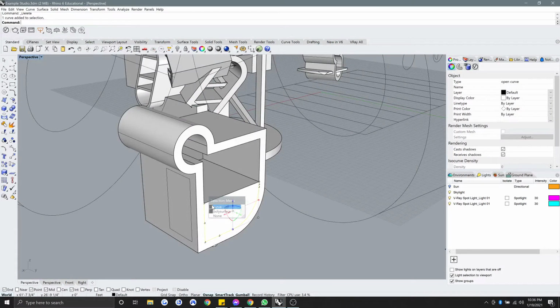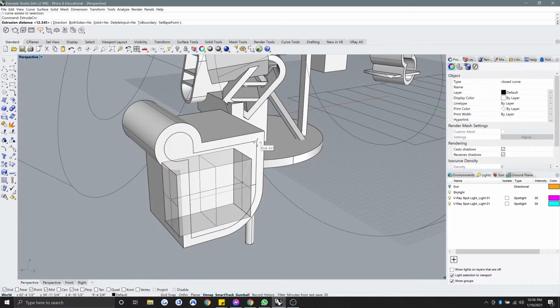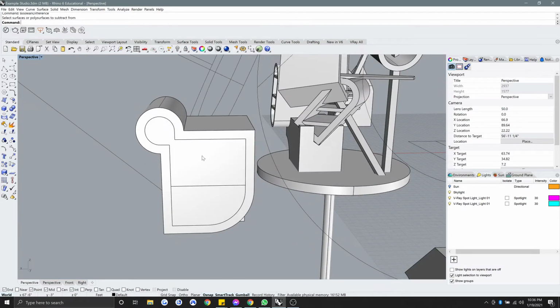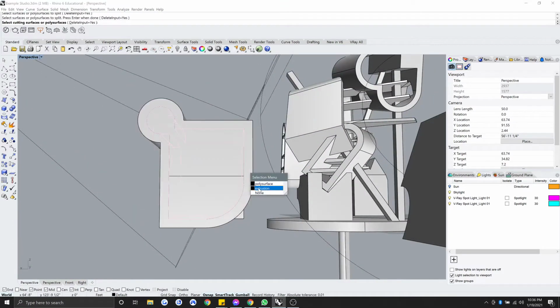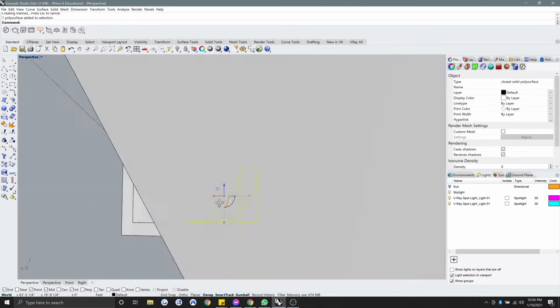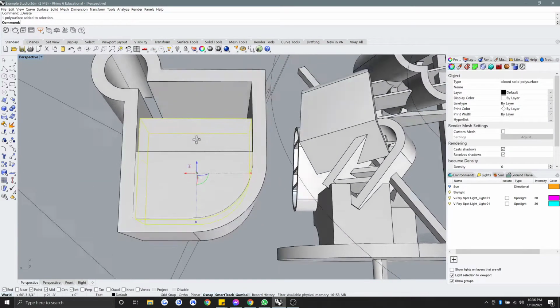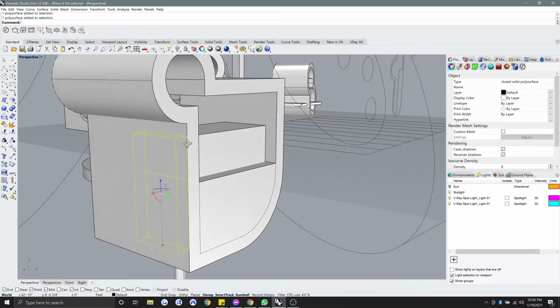On this side, we have the original two curves. I'll rejoin them, re-extrude them back, extrude this to this wall, Boolean difference, actually Boolean split this shape, the one that is too long, by this one in the middle. And you'll see that the part I'm deleting here is that extra part. So now when I delete both of these, this shape is actually this big, including this little bit that's stuck in the wall.